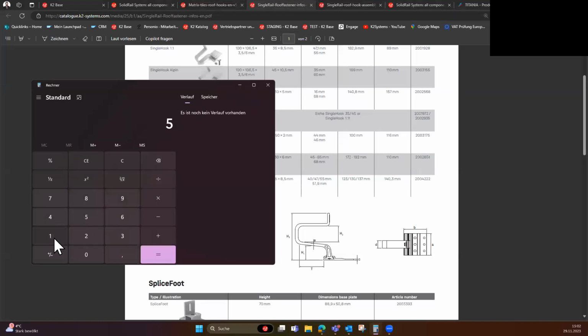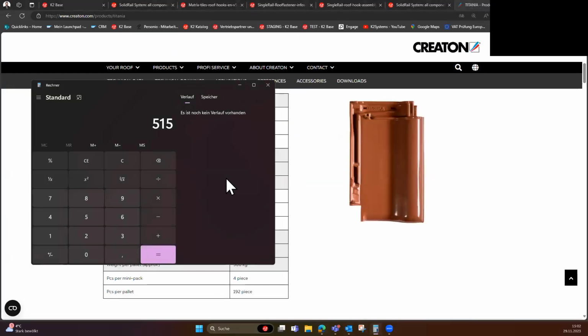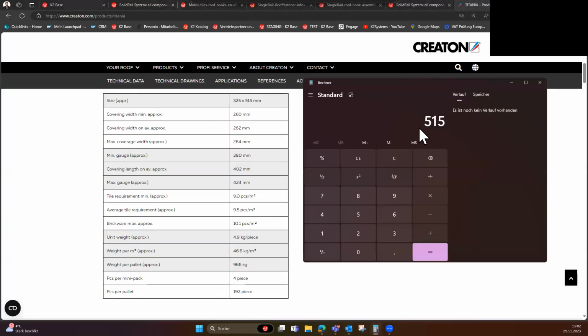So we take the size of the hook, 550 millimeters, and we are taking from it the minimal button distance, 380 millimeters. And so we have now 135 millimeters and this is supposed to be our extension arm length.